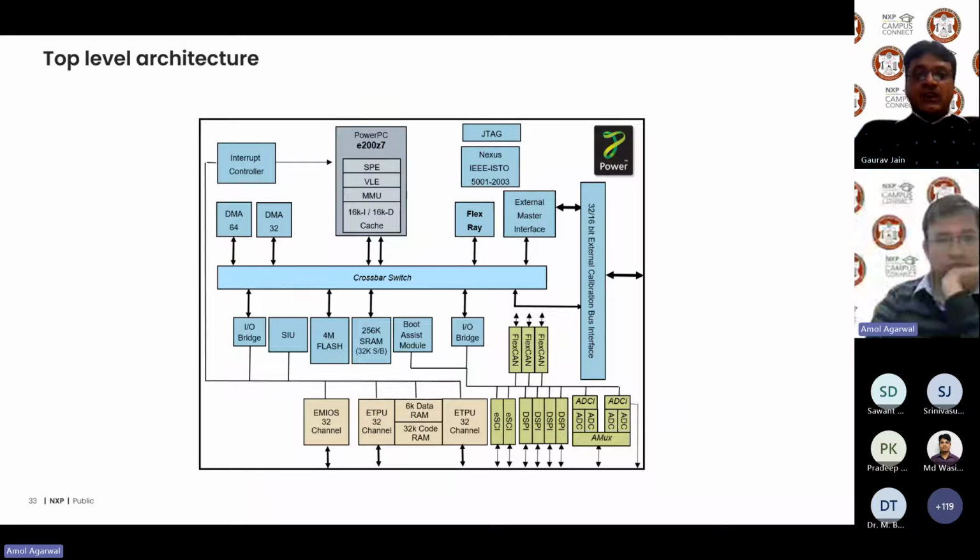So as part of the architecture specification, we get this kind of block diagram where it is captured, right? So just giving an example, in the market, assuming the system engineer comes up with that we need so and so performance from the microprocessor. Then depending upon the options available, the architecture team and system team work together to come up with a particular microprocessor that should be there on this particular chip to meet the customer requirement. And similarly, all the other IPs that you see here will relate to one or another customer requirement. So that's how this top level block diagram is put together by the architecture team. So that's one of the starting points to start designing the SoC.